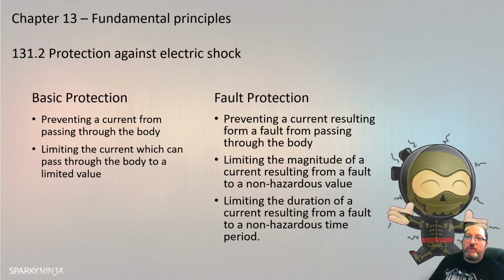Okay, so isolating transformers, extra low voltage supplies, having safer voltages, touch voltages, bonding. But for basic protection, we're actually thinking maybe about electric fences kind of thing. High voltage, very low current. The current is limited to a non-hazardous value.